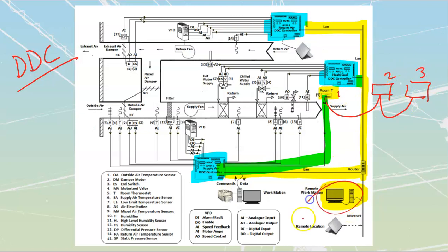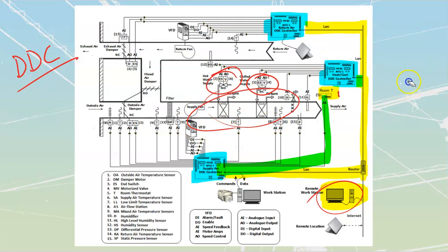Then inside of my software, I would type in that thermostat number 1 is in this room, and that room also has these heating and cooling manifolds over here that are controlling the air that goes into it. Because in a lot of cases, all of these manifolds are spread throughout the building, it allows us to do a lot of network control.